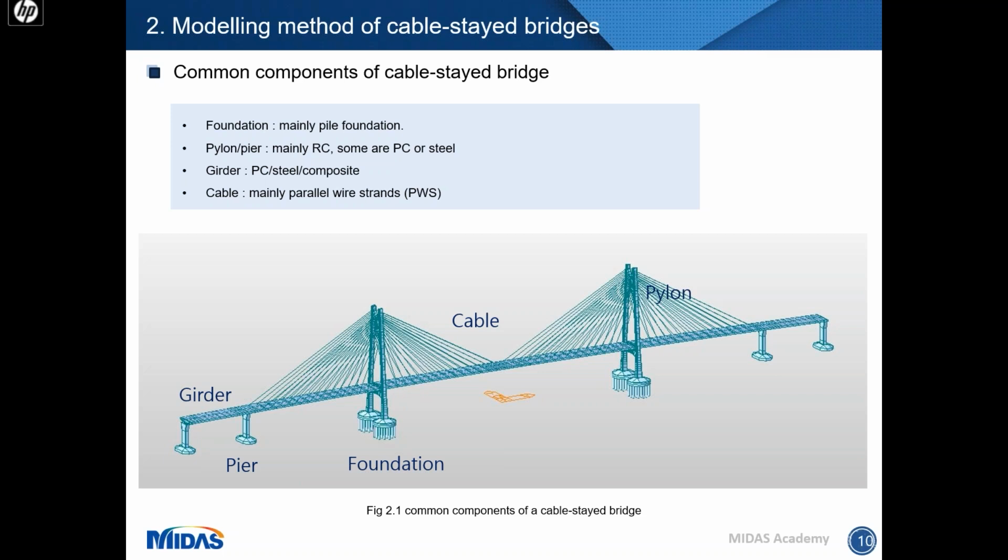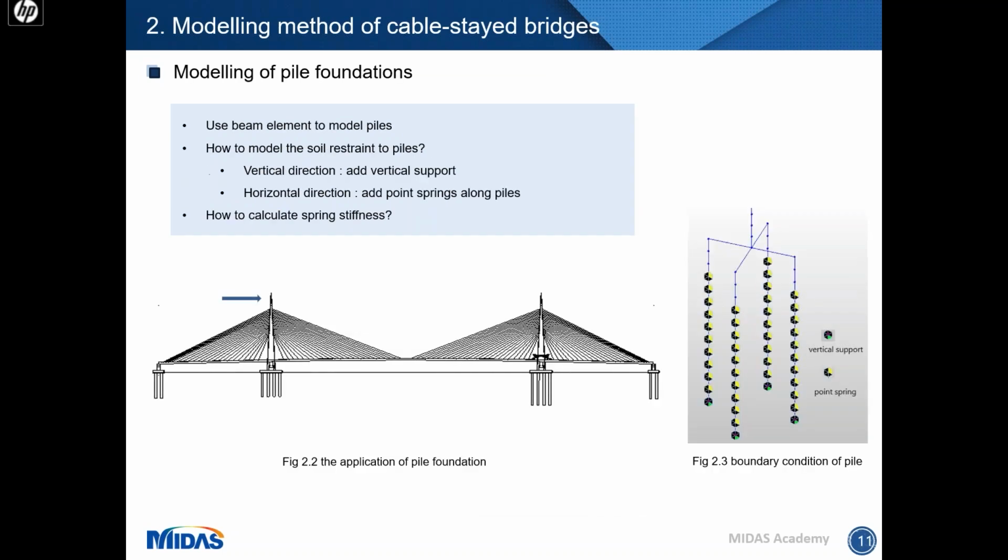For the cables, usually we use parallel wire strands, or PWS. Now I'm going to show you the modeling method of each component. For the pile foundation, the pile itself is easy to model because we can use beam elements to model piles.